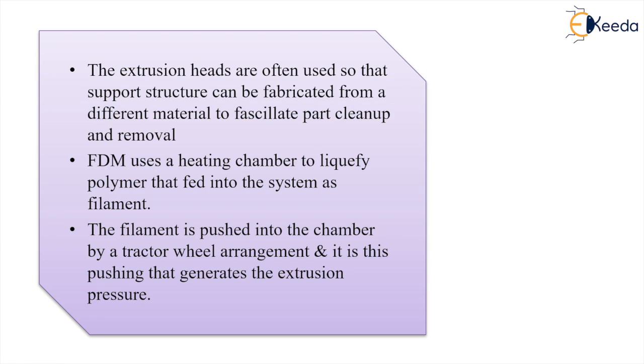This FDM uses a heating chamber to liquefy the polymer, which is fed into the system as a filament. So here the raw material is polymer. Like in the extrusion process there is a billet, here the billet is made of polymer and you are heating it and passing it through the required system as a filament.